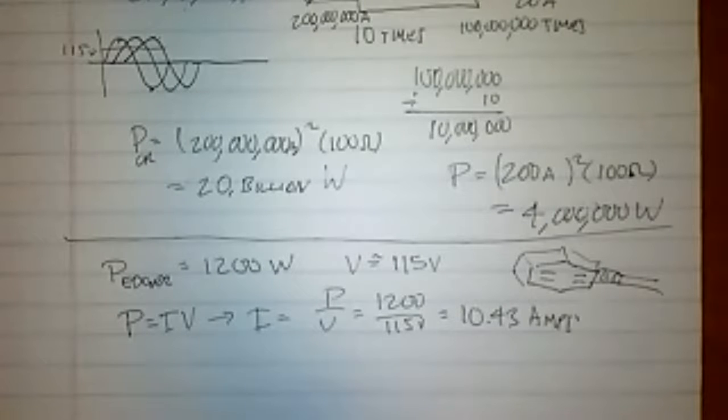I suspect we could, because I'm the kind of guy. Another thing is that companies make certain small cords only to a specific length, which limits you from dragging it around outside. They might be 6 feet or 10 feet or 12 feet, but not 50 feet or anything like that. Yeah, and if you had a longer one, since R equals rho L over A, you would get a larger resistance and cause a little more drop in the voltage. It would be nice to have that kind of thing, but we do have other protections. Specifically, they say not to go over a certain number of amps, but if you don't know how to get your amps from your power, then you're out of luck.